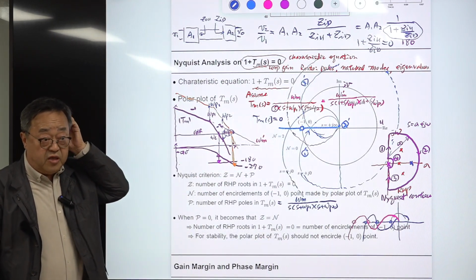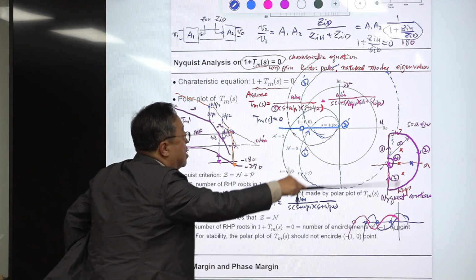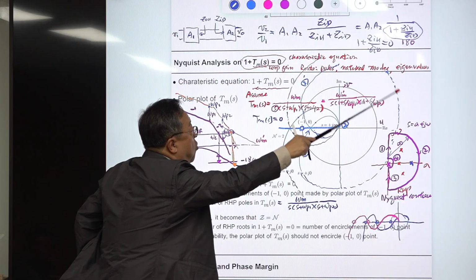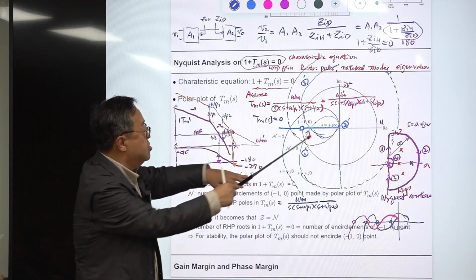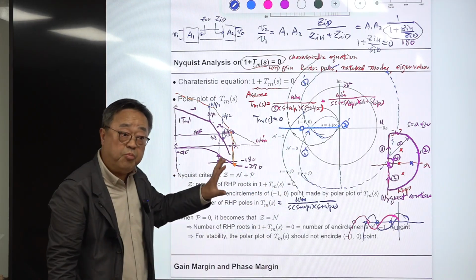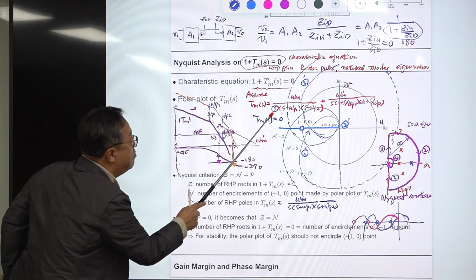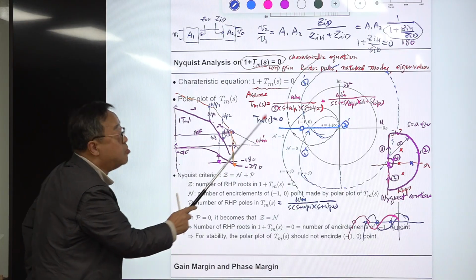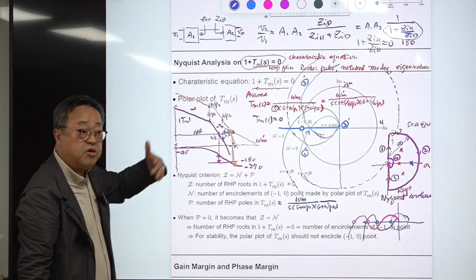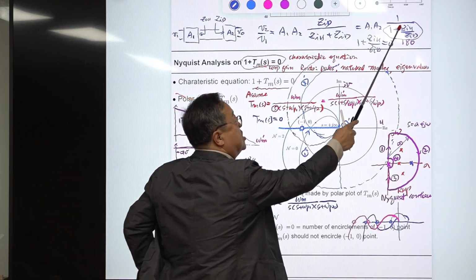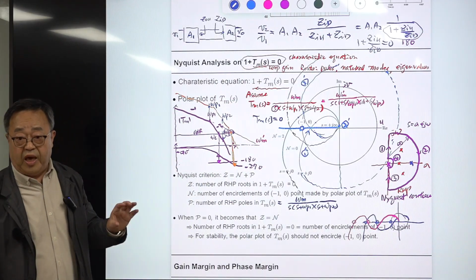All right, that is one example. For that case, usually the loop gain is something like this. It starts out here and goes back like this. Okay? Still, you can apply the Nyquist criterion under this strange shape loop gain. It really doesn't matter, the shape of the loop gain. This is the typical example because of the presence of this. Okay? So this is very general. In here, there is no feedback loop. But still, you can apply this. And this quantity, GIU divided by GID, can be considered as the equivalent loop gain of the system.